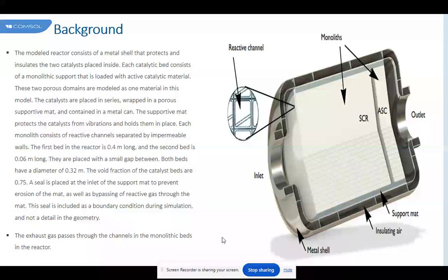Comparing the permeability of the ring and core monoliths is indirect because the flow model considers the hydraulic entrance length. However, a quick inspection can be performed by analyzing the asymptotic friction factors in the fully developed region, that is, by comparing the factor f·Re of both monoliths. According to the data in this simulation, the apparent permeability of the 900 per 2.5 monolith is only 40% lower than that of the 400 per 6.5 one. However, such a difference is sufficient to significantly impact the fluid distribution.